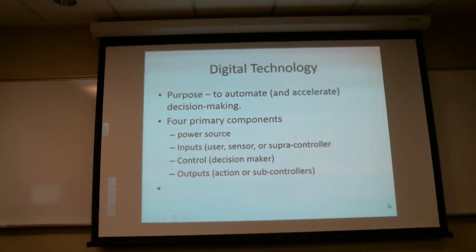And we've seen that. For example, in the world of turbine engines, we've gone to off-the-shelf electronics subjected to very high levels of QA. They're so light and so small that you can just put 4 different computers in 4 different locations. Each computer works in tandem with the others to monitor each other. If 3 of them decide one of them isn't behaving right, it's taken offline and the other 3 take over, and on and on. Of course, turn on a big red light in the cockpit. So there are ways to achieve redundancy.